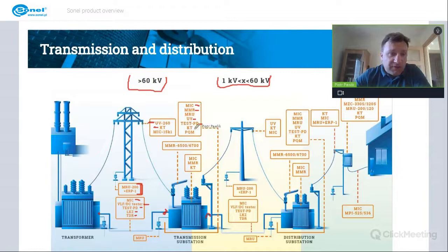We can use thermal imaging cameras, so KT series, to check for any overheating elements. And we can use the PQM meter to make sure that the power quality is correct of the incoming power and the outgoing power as well.